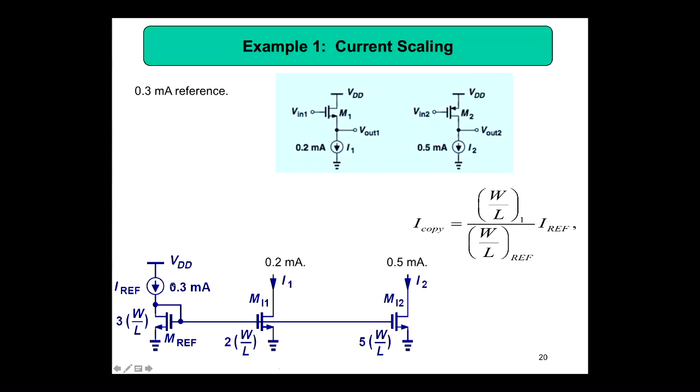So what we have done is, the golden current is 0.3 milliamps. You connect 3 NMOS transistors in parallel, which is why we have written 3 times W by L. And then here we connect 2, so 2 times, and you get 0.2 milliamps. And when you connect 5 in parallel, you get 0.5 milliamps. Now you got it. Now you can just connect this here, because you can replace this I1 with this M1 part, and I2 with this part, because from this point you need 0.2 milliamps.